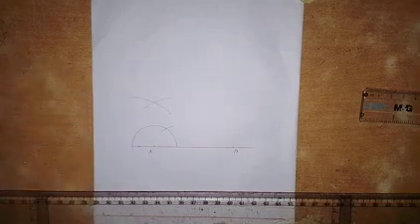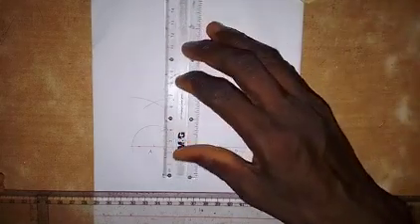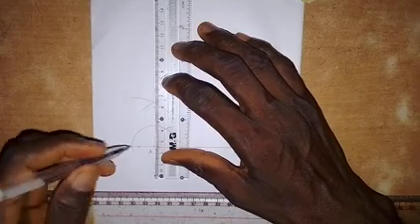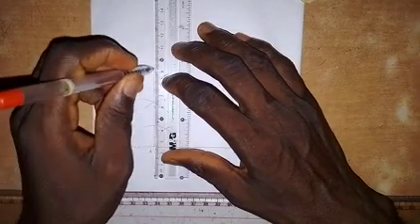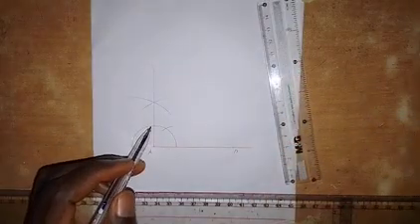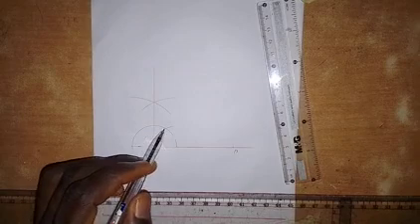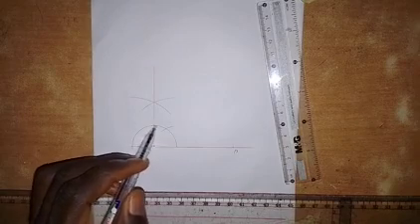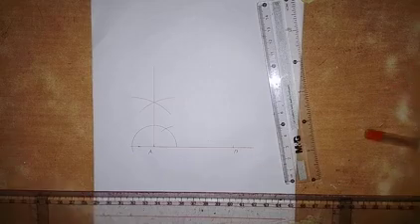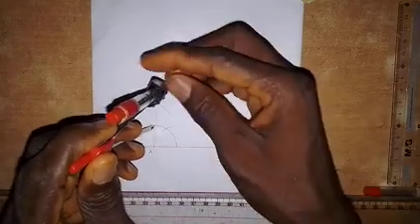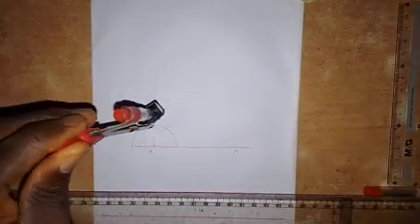Okay, so we are going to draw a line through the point of intersection of the arcs from point A, and it goes like this. Alright, so we have this. Now the angle from here to here on this semicircle is 30 degree. So we are going to bisect this 30 degree. We are going to divide the 30 degree into two so that we can get that 15 that we have to add to 60 degrees.